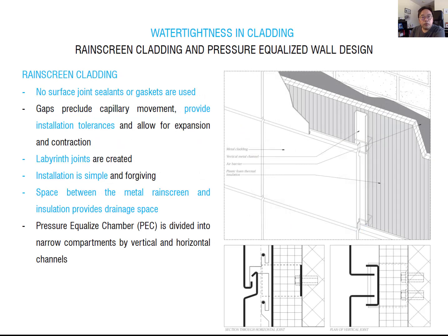Now we talk about the RAINSCREEN system. We already discussed the RAINSCREEN system before. This is a possible RAINSCREEN system. I am introducing this system because most cladding systems don't use sealant and backer rod between the panels. They are not going to use the sealant because it doesn't look good, and also it's too much work. So they use more of a dry stacking method, a dry assemblage method, panel and panel, and then simply assemble over this channel.